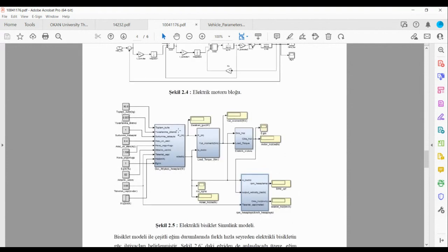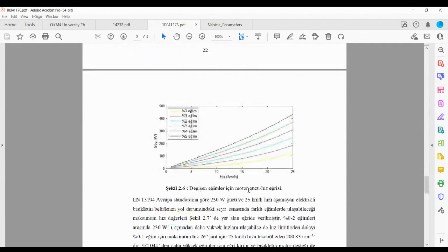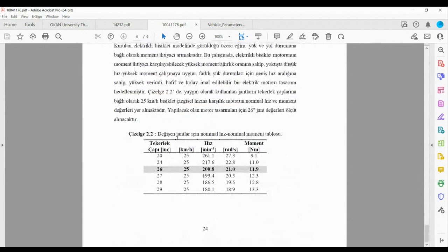Here, power needs calculation according to longitudinal dynamics, load torque calculation, your electric machine, and you will also add speed, which will be variable here. You will add a driver profile. Also, you will add a battery. In one driving cycle, you will show me how much battery energy is consumed. Also, your vehicle range. Also, another power needs. Okay, like this one, you will send me a graph, etc.